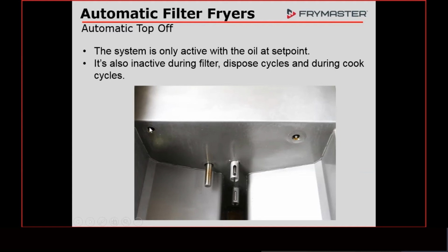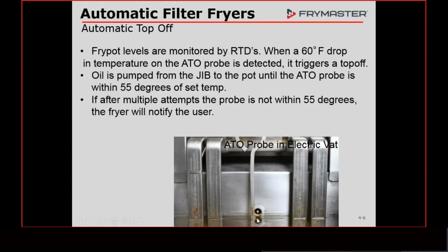And you guys that work on these have probably seen this before, where this just fills up with debris. That debris has to come out of there. We have to keep that clean. The whole idea behind the socket here that can fill up with debris is that when the oil comes up to this line, the oil first goes in that socket and surrounds that probe. That just makes the response quicker. There's more surface whenever that oil can go inside there. Whenever it shuts off, that oil level is right on that line right there.